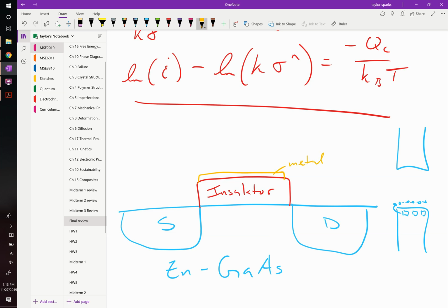The reason they call this a MOSFET is that it's a metal oxide semiconductor, so you've got metal oxide semiconductor, MOSFET. And then FET comes from field effect transistor. The field effect means that when you put an electric field across this thing by applying a voltage between your substrate and this metal gate, since this doesn't conduct electricity, as we learned with parallel plate capacitors, you could imagine a scenario where you pile up negative charge here and positive charge here, right? And in doing so, this P-type material, which is normally chock full of positive charge because it's P-type, now has a region which is N-type, right at the skin of this thing, okay?